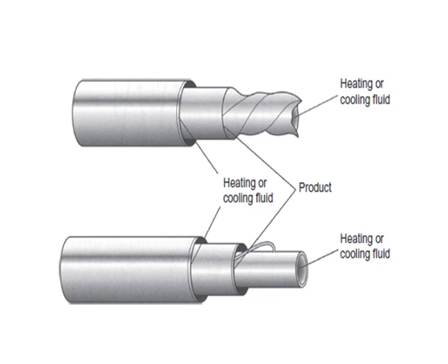This type of heat exchanger product flows in the inner annular space, whereas the heating or cooling medium flows in the inner tube and the outer annular space. The innermost tube may contain specially designed obstructions to create turbulence and better heat transfer.